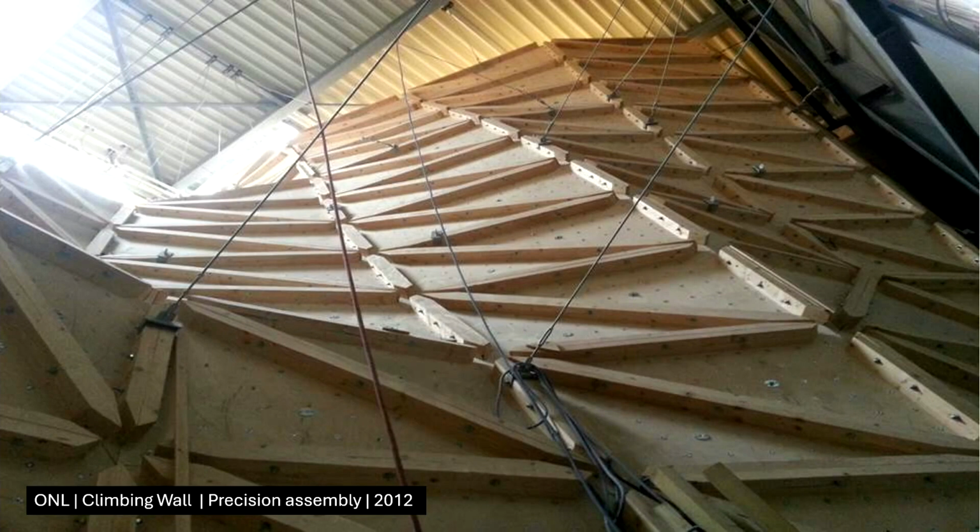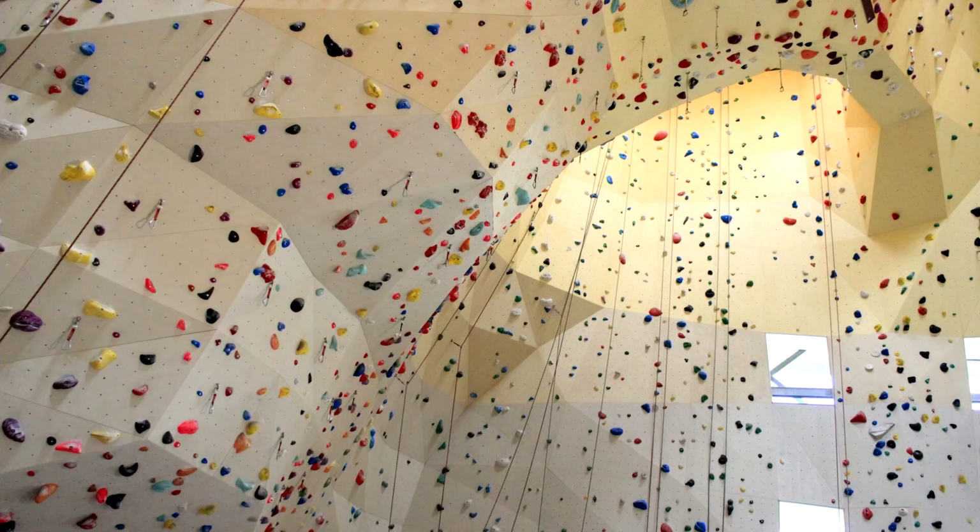And you see the forces coming down here transfer to the skin, so it works together. Structure and skin work together structurally, transfer to the skin, transfers to another beam, transfer to the skin, etc., until it goes down in all directions. And again, you can easily take out one, and you can build anything. You can take out one, two triangles form a rectangle, so it's inclusive for more traditional geometry as well, but especially very suitable for building complex structures, and for climbers this is ideal.